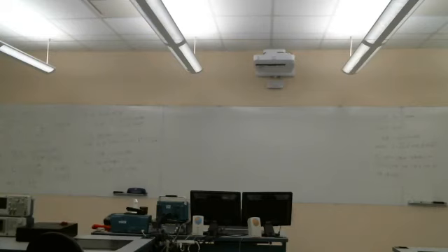Someone noticed that if you take the product of these two measured values, in the theoretical equations here we've got tan beta L, here we've got cotangent beta L, which is 1 over tangent. So the tangent-cotangent product goes away. Here we've got plus j, here we've got minus j. That product is equal to 1.